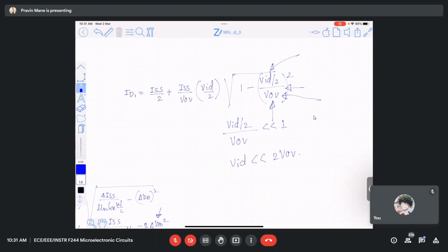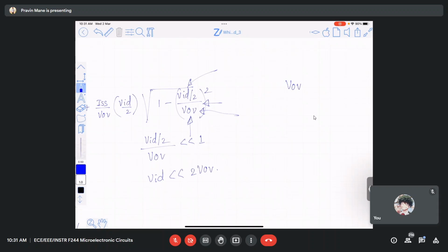We get to the linear region, right? So one is that there will be a reduction in the output voltage swing. But what is the other reason? What is gm? Twice ID divided by V overdrive, right? If I increase VOV, what is going to happen? So gain will go down. So these are the trade-offs. It is not so simple: by simply increasing VOV, I cannot make the circuit linear.